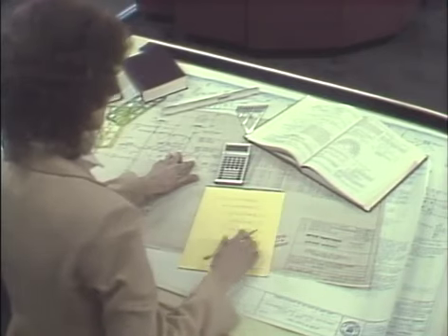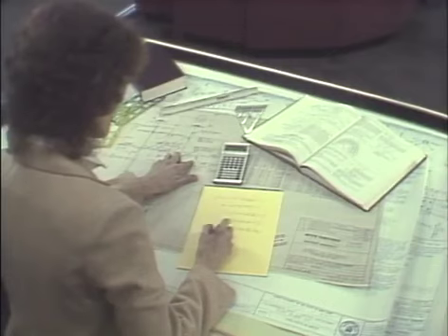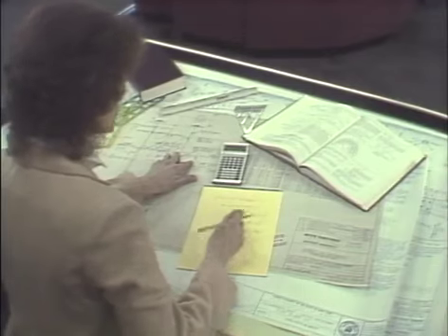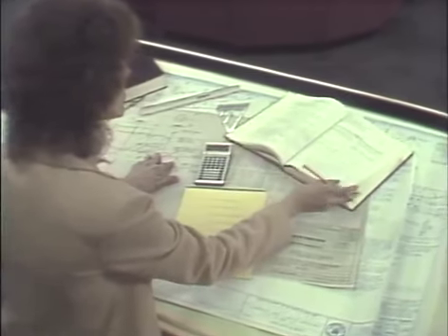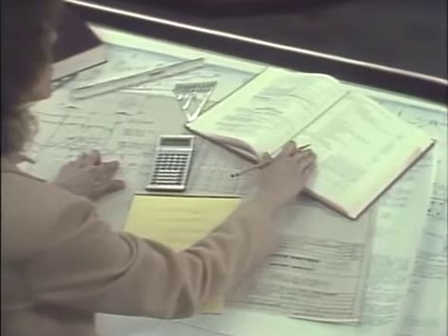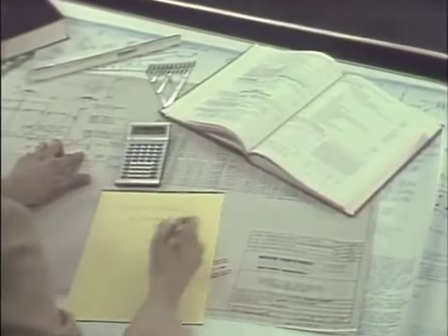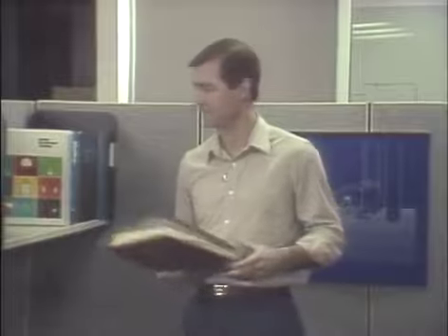They start with information about the power available and the power required. They look at the factors that determine the amount of power and power loss in the system, such as transmission voltages, conductor size and material, and the possible arrangements of a variety of structures. They determine how all these things will affect the power transmitted and received, and consider their design options. After selecting the best option, the designer can adjust the design to ensure the most efficient construction, maintenance, and power transmission possible with a minimal amount of power loss.